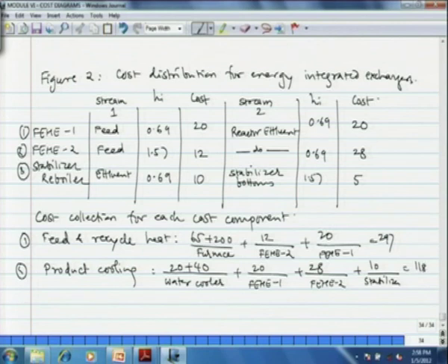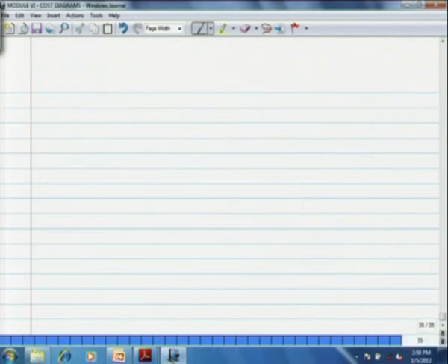Next, the reactor. Here we don't have any allocation, so direct $200,000. Then the next one is the recycle compressor. There also the cost remains same as the previous flow sheet. There is no further distribution. $50,000 capital, annualized capital cost, $60,000 power, so total $110,000.